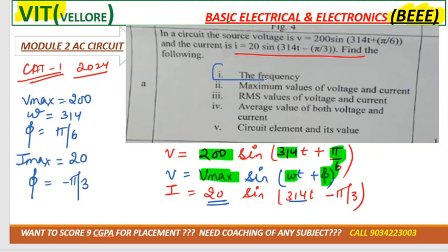Now let's see what they have asked. They asked you to calculate frequency. So we know omega is equal to 2 pi f. Omega is 314, so 314 is equal to 2 pi f. So f is how much? 314 divided by 2 pi. Pi is 3.14 only, so you will get the frequency as 50 hertz, right?